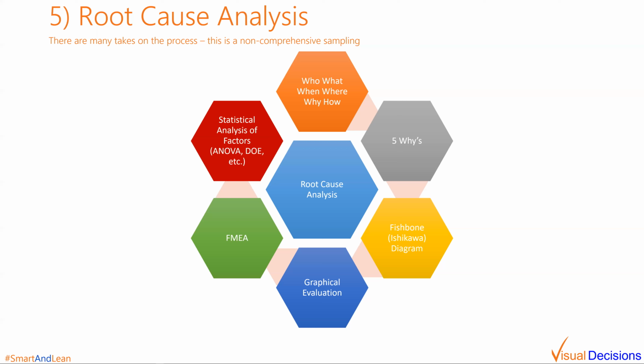Smart manufacturing systems are fantastic for this type of problem solving. Because they're so data rich, most of the information you'd like to know about the process can be charted and shared for analysis. And FMEA. In another webinar, I've described how to create an evergreen FMEA, or failure mode and effect analysis, that is continually updated with information from the shop floor. Based on the symptoms observed from the shop floor, this tool can be used to see if there are known causes for failure that you should investigate right away. We'll look at the rest of the methods on the following slides.